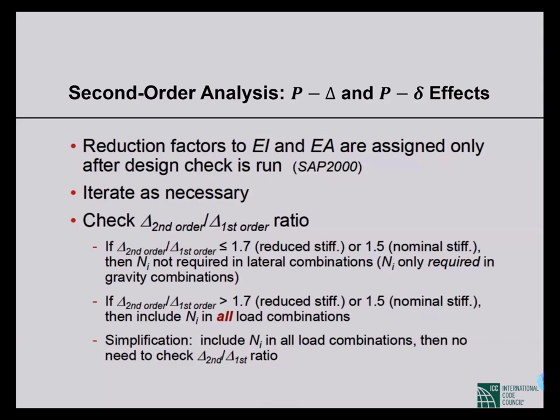And so we have to check this for each and every load case. So for some load case like dead load, wind load, and then notional loads, or dead load, earthquake load, and notional loads, for each of these load cases, the scenario may be different.